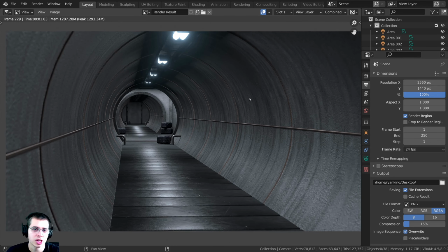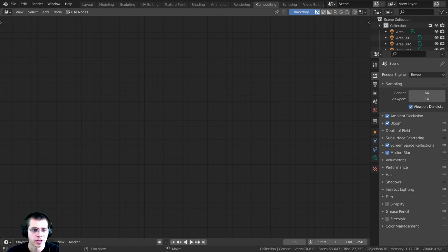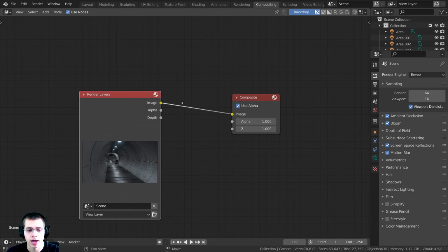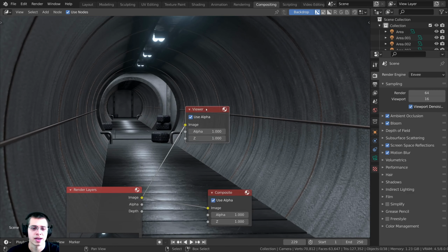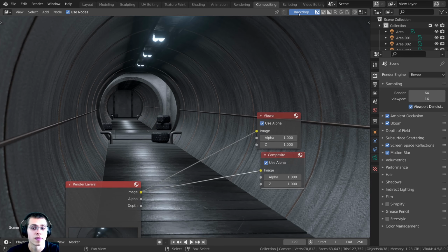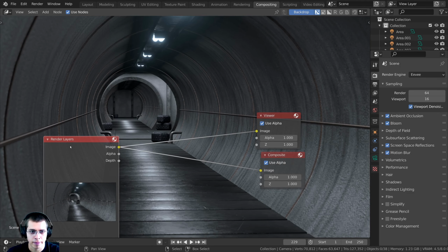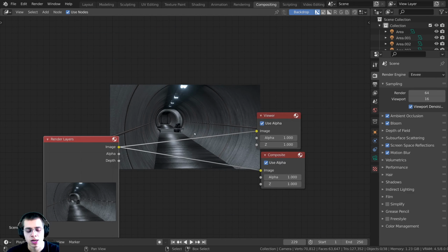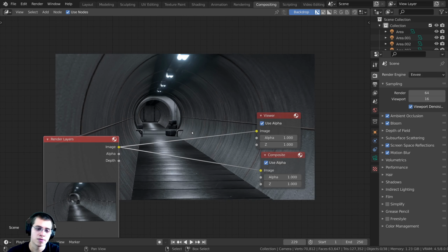And we can now just do a little bit of compositing to make the final image look really nice. So let's just click right over here on the Compositing tab. All right, let's just click on Use Nodes to use the nodes. And then we did already turn on the Node Wrangler add-on. So I'm going to hold down the Control and Shift key and click on the render layers. And that is going to add this viewer node so we can preview it in the backdrop. And then also, if for some reason you can't see the backdrop, you might need to turn on the backdrop button right there. All right, now my background is a little bit too big, so I'm going to press V, and that is going to zoom the background out. You can also press Alt V to zoom in and V to zoom out.